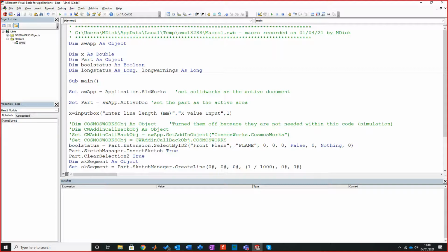Now, there's a few ways of being able to do this. You've got to think, if I put 1 in there, that will be 1 meter. I've asked the user to input in millimeters. That means instantly, if I do something wrong here, if I don't change it, they're going to input 1. It's going to come out in meters or 500 and so forth.